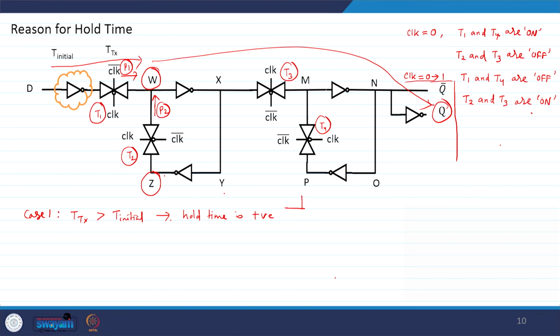So, I have a clock edge and I have a data. So, that means this distance is positive. This is clock, this is data. Okay. So, your data should be available after the rising edge of the clock in this case, in case 1. In this case your data should come after the rising edge of the clock such that it will be sampled by the clock.